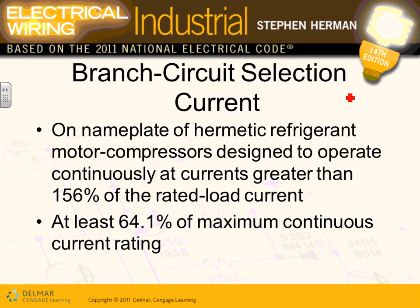The next one is called branch circuit selection current. Branch circuit selection current, guys, is exactly like rated load current. It's defined by the nameplate of the hermetic refrigerant motor-compressor, designed to operate continuously at a current greater than 156% of the rated current. So what they call branch circuit selection current is typically equal to rated load current. Typically equal to rated load current.